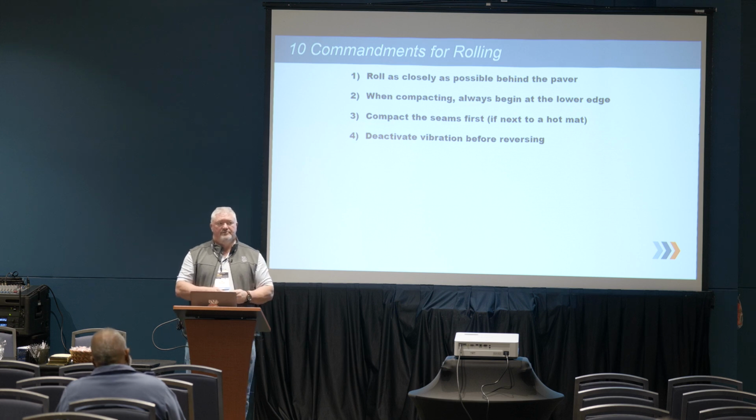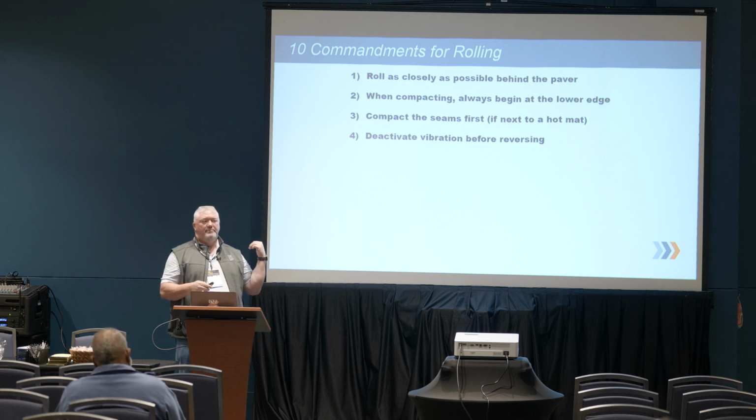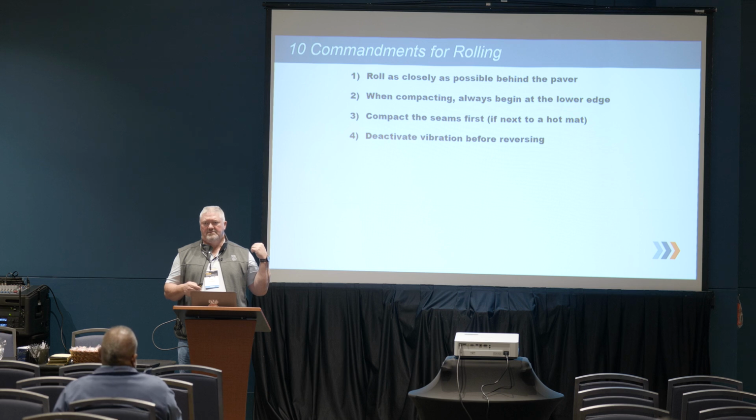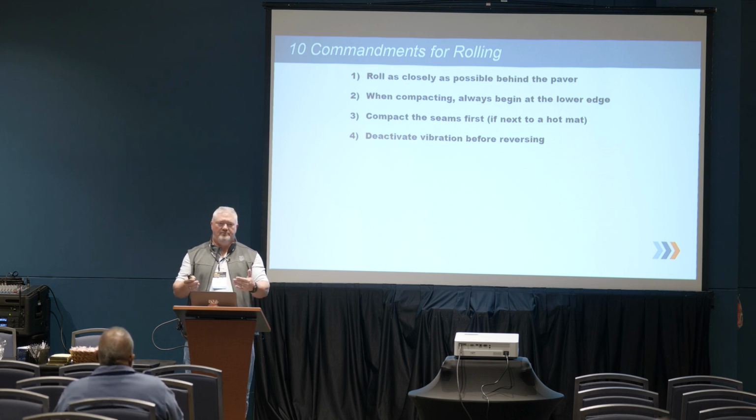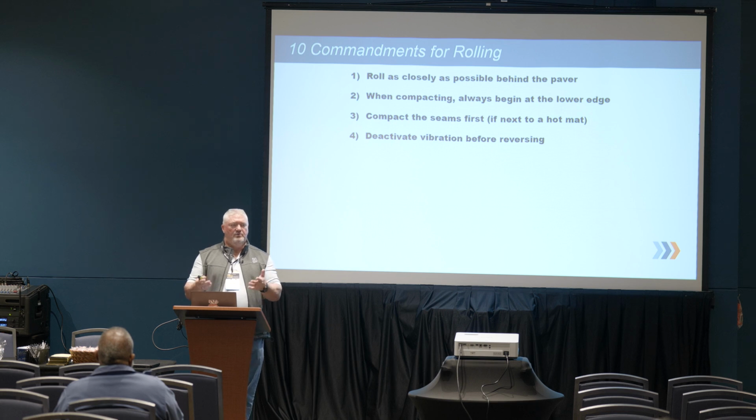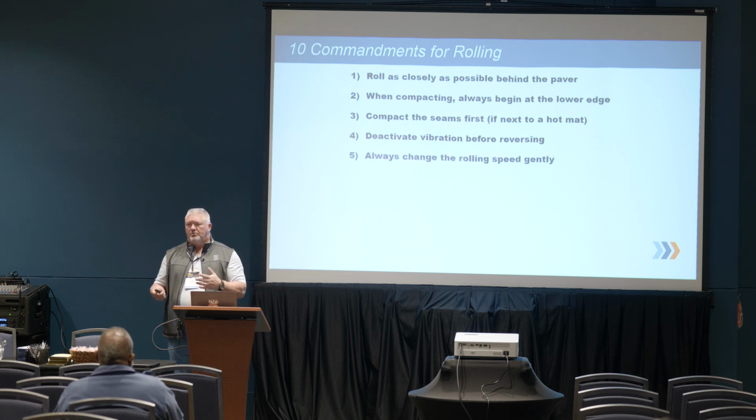Deactivate vibration before reversing. I throw that in there and people think, well, that's crazy, that's common sense. You'd be amazed how many times I get on jobs, people forget to shut the vibes off when they come to a stop and back up and wonder why they got a bump there. It does happen.